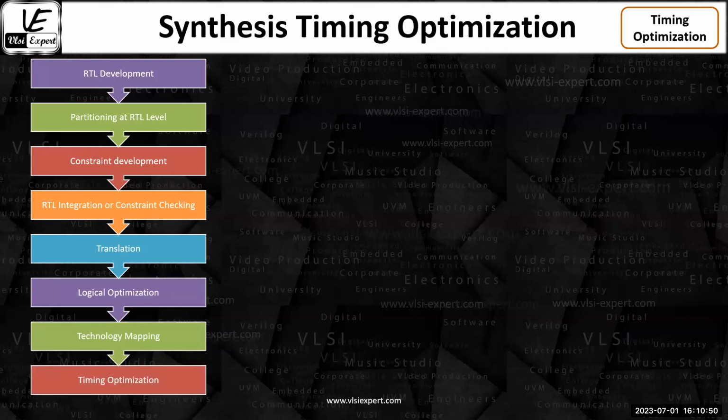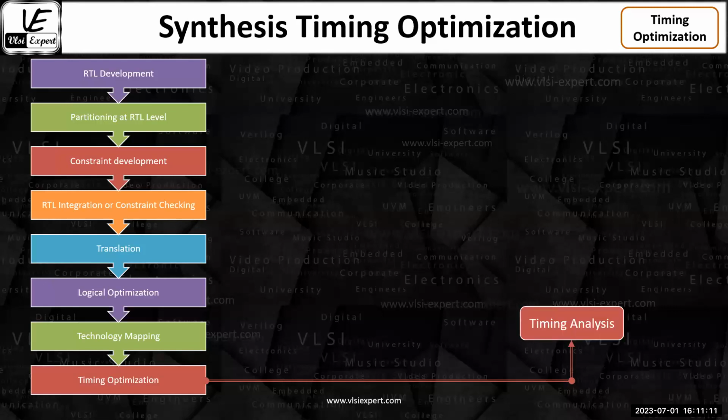Once you do the technology mapping, right now I'm checking timing optimization. So this portion is related to timing. I will focus more on the timing part, but almost the same flow goes with the power side also. So now let's talk about timing optimization. In timing optimization, I do the timing analysis, which is static timing analysis. After synthesis, once it is converted into the circuit, that particular NAND gate is mapped to a first level NAND gate. Let us suppose that NAND gate is mapped to NAND 1.